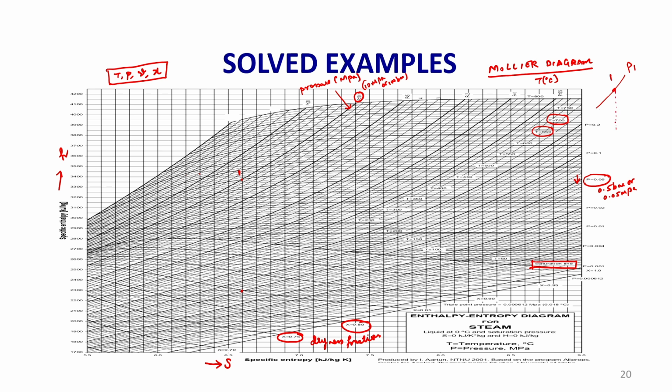Draw a 90 degree line, a perpendicular line, to any distance; this point will meet the low pressure line. That is okay. I think this is 100 bar and 500 degree centigrade intersection, and this is the 0.5 bar line. So draw a perpendicular line from point number 1 to where it intersects the 0.5 bar pressure line. That is this one, and that will be state number 2.